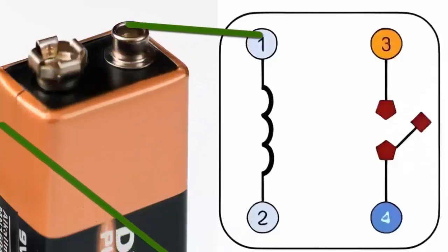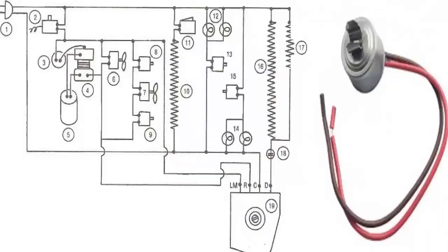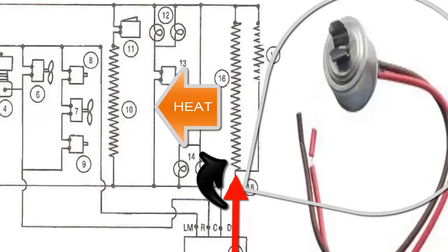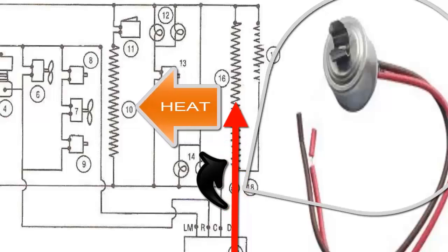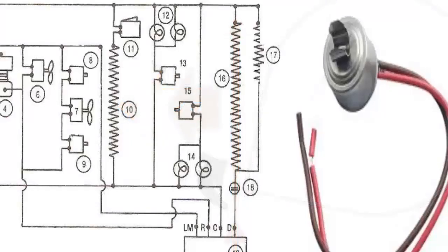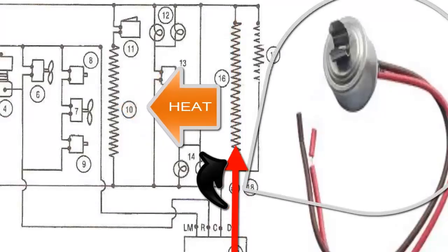6. Bypassing the bimetal. If you suspect the bimetal isn't closing the circuit, you can bypass the wires feeding it to check if the heater warms up. To do this, defrost the evaporator, remove the bimetal, and directly connect the heater's wires. If it heats up, it means the heater is fine, and the issue is with the bimetal.